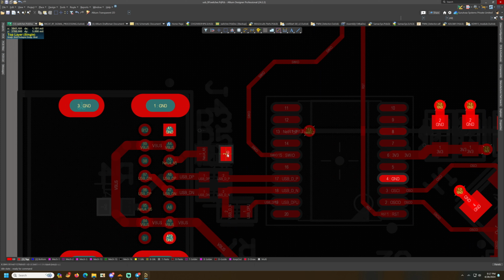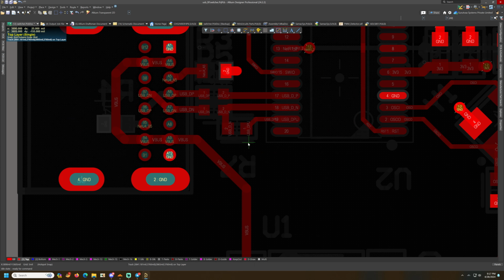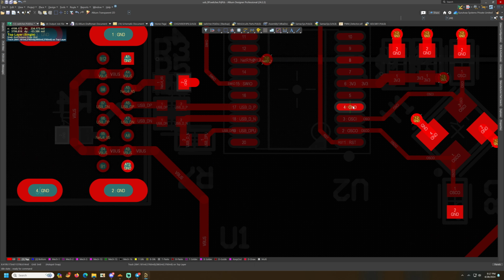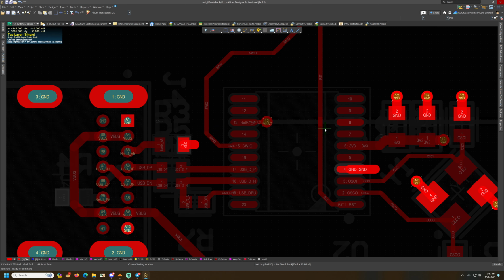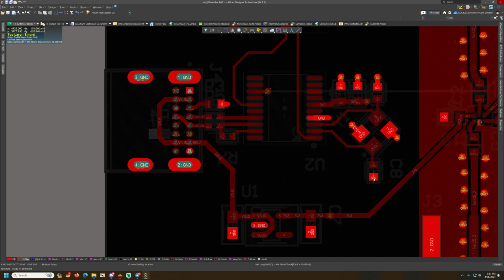I have seen cases where having fewer vias have caused the impedance to not be 50 ohms, to be rather some arbitrary value which deviates from the desired impedance value.